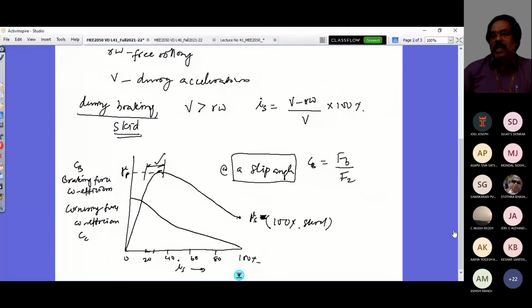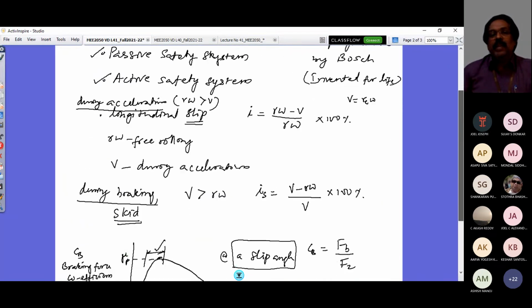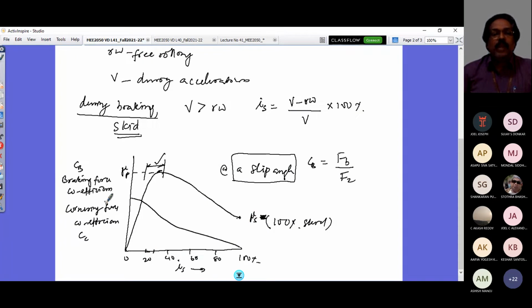So we have looked at this for understanding of the ABS functioning. We have to look at this graph; it's very important. The ABS essentially makes sure that whenever braking torque is applied, it operates in this desirable range, so that it will never let your vehicle wheels lock. Wheel locking happens suddenly, falling to this. So this portion never happens if we have an ABS, and this ensures maximum braking effort to have your vehicle stop at the shortest distance, and at the same time sufficient cornering coefficient, and hence cornering force, to counter any lateral disturbance that acts on your vehicle. That is why you have to correlate this graph with what you have witnessed in your video.